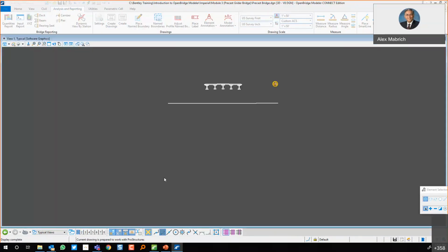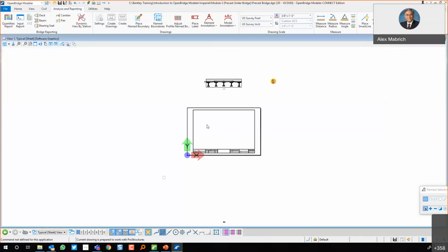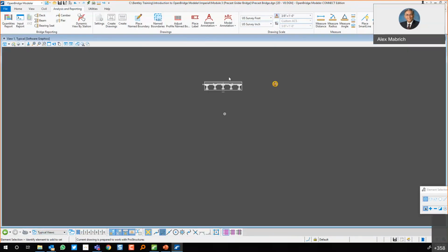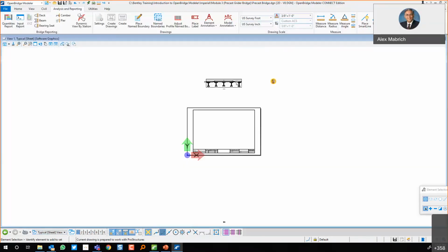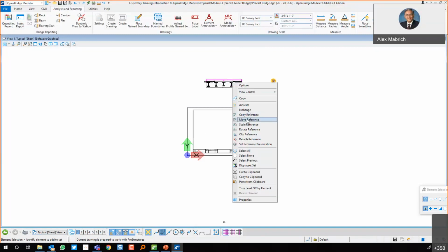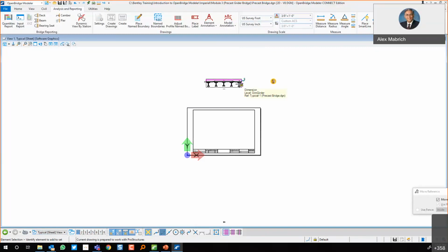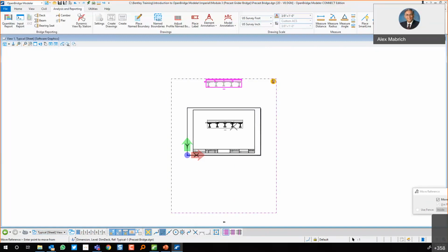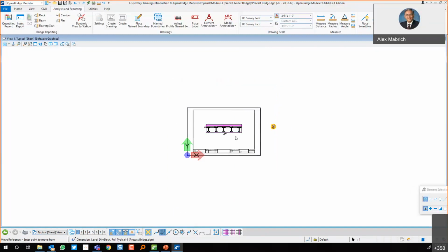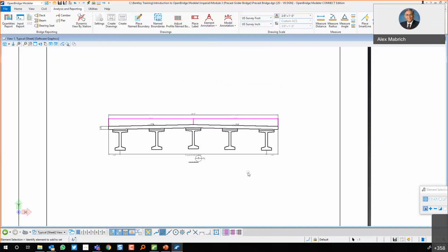So it's doing it twice because what it's giving you in the drawing is text dimensions. On the sheet itself, it's just doing that. So what you can do then is move the reference. What I did was press the right click, holding that, it activates this menu. Then I just go to move reference and put it there. So now you have your sheets there.